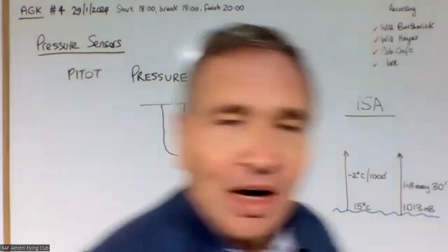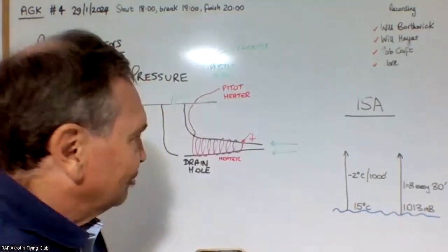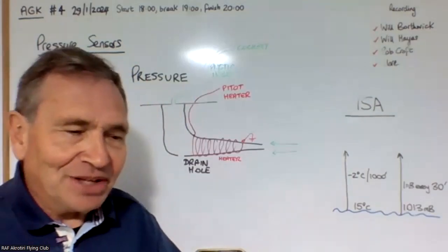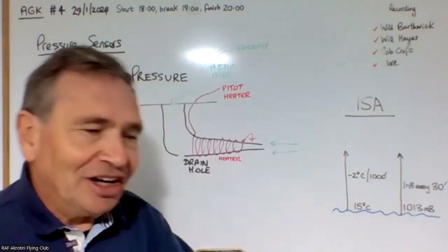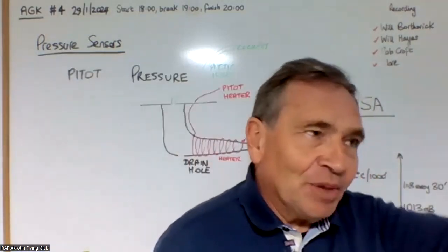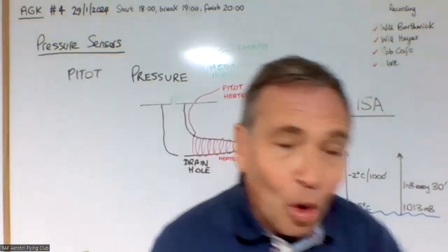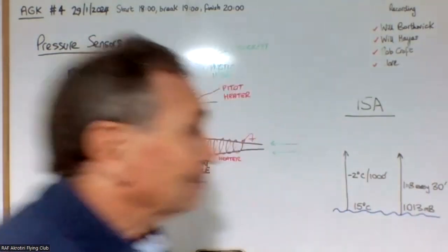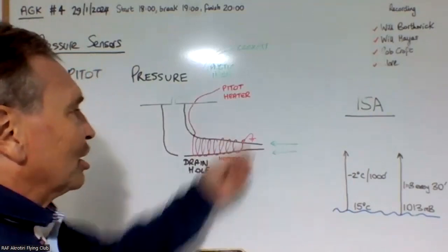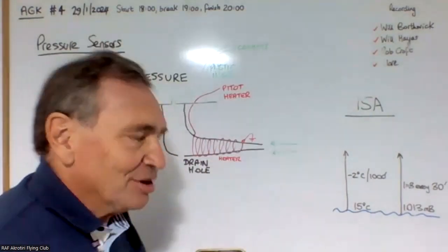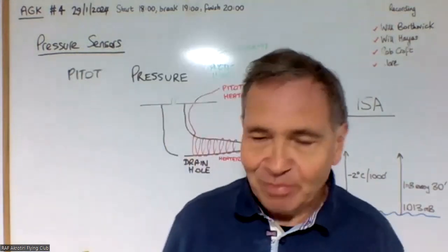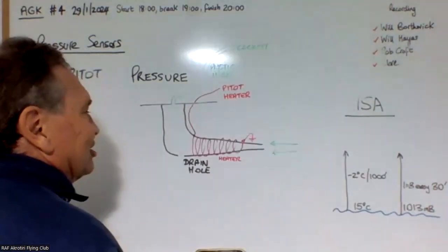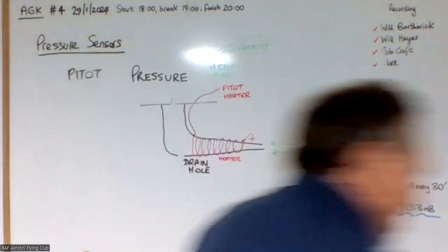I mean, certainly more experienced pilots, you tend to find that if you want to check the pitot heater, you turn the pitot heater on, leap out of the plane, quickly check to make sure it's getting warm, leap back into the plane and turn it straight off. You don't include it in your walk round drill that also includes doing the fuel strainers, checking the propeller, checking the brakes and all that sort of gear, because by the time you've done a walk round check of the rest of the plane, this has probably flattened your battery.